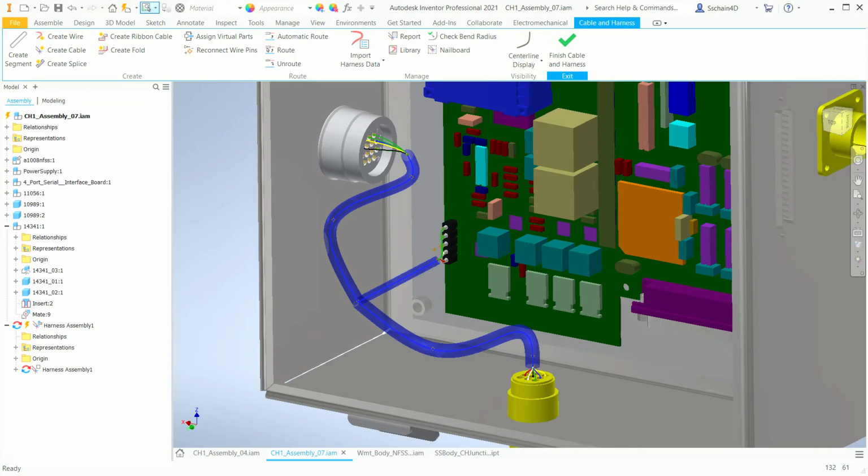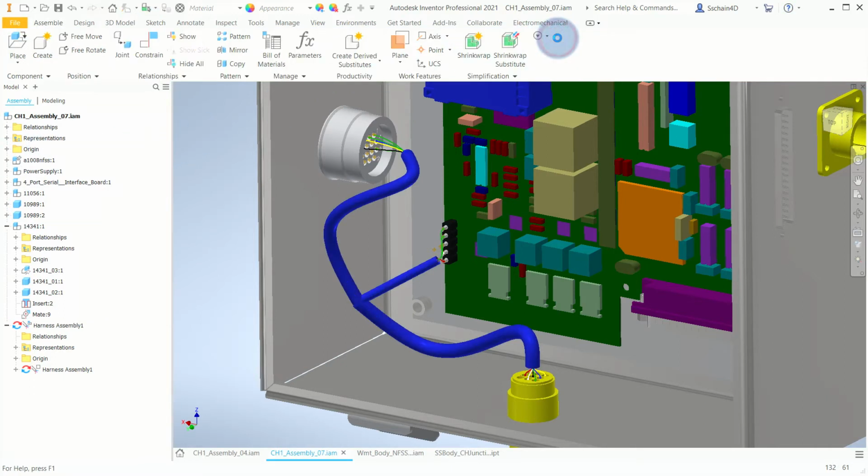So authoring electrical components can be done once you have wires routed. It doesn't matter at what point you want to do it. You can author electrical components to a custom library. Once you have libraries set up in your project that are read-write, you can use the Manage tab to publish a part to a custom library.